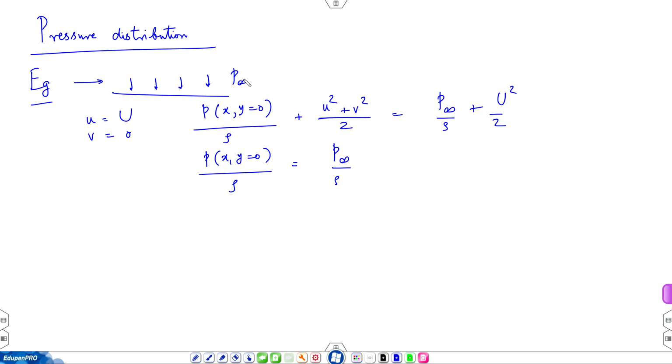So, you have let us say a wind tunnel where speed is very high, viscosity is very small, plate length is substantial, you are going to get high Reynolds number, you measure pressure distribution, it will turn out to be nearly constant, practically constant. So, this result is experimentally validated.